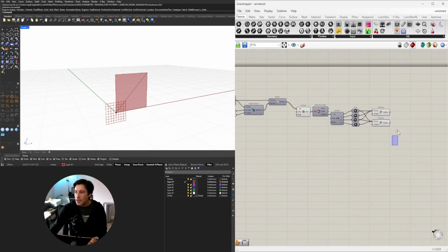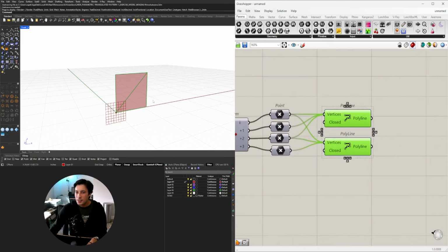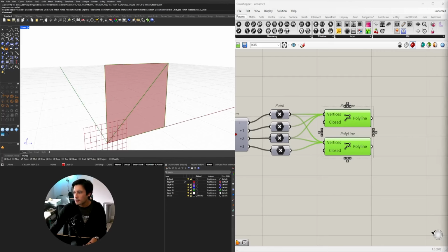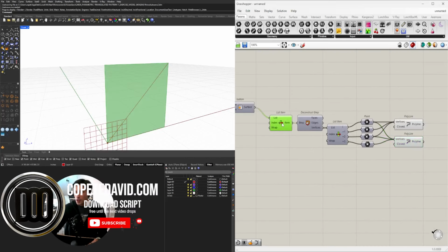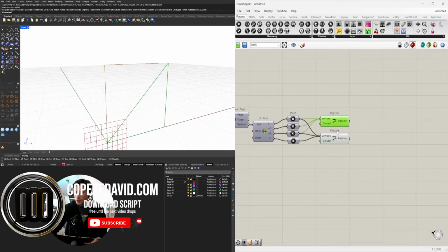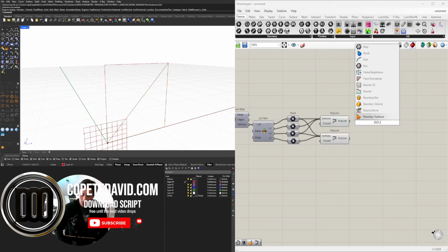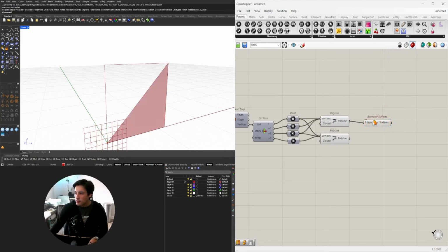All right, now at this stage, we need to create the pop out of the triangle here. So at this point, we got these two, but we also have the original surface. So what I'll do is I'll take this, disable preview, and now create a surface bound by that polyline. So let's go to boundary surfaces for both.